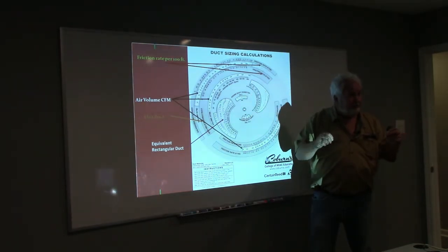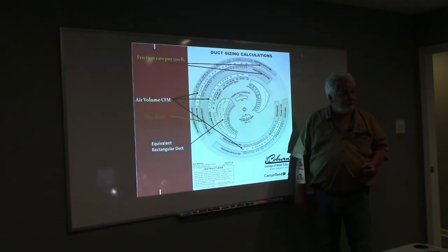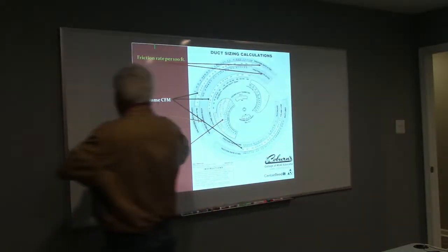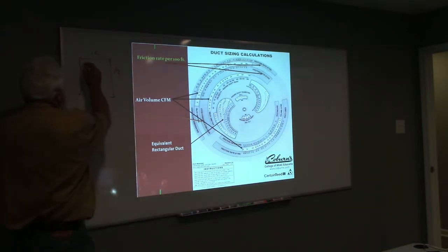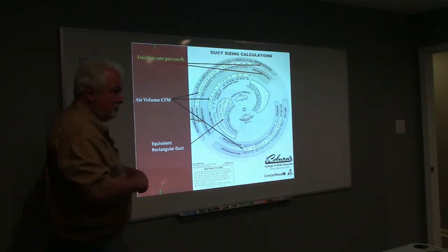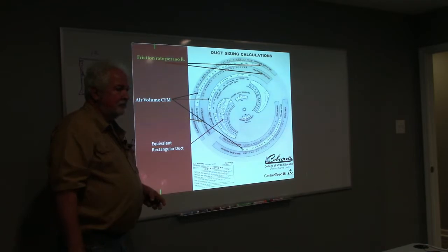I've got to get to the inside. Okay, so if I have a 12 by 12 duct with 1-inch liner, what's the actual size that we're looking at? He's giving you the dimensions. You've got a 12 by 12 duct with 1-inch liner. What is my free airspace inside of this duct? 1 inch off of this side, 1 inch off of this, it'd be 10 by 10, yes? Good? So we don't look at our CFM based on 12 by 12. We look at it based on 10 by 10. So y'all would take this little thing.